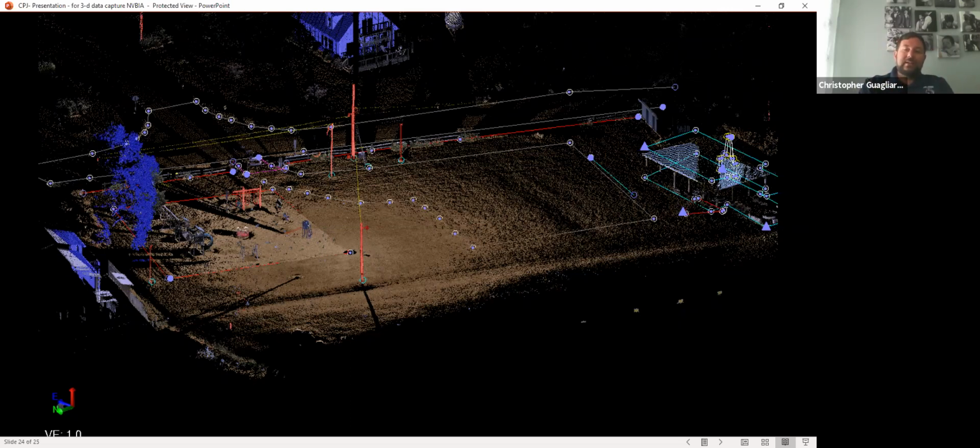I tend to make marks or just do different things in the house so I can register it. Look for different parts of the house to register it in there and make them tight. But like I said, you can use targets. So if I was doing my house here, I would scan one room, go right to the next scan, and keep going around. While I'm doing that, it's going to register when I get done, and then I can start making measurements in my house.